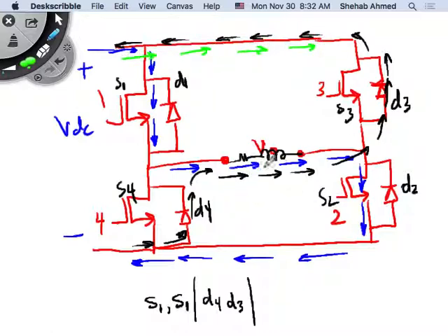Remember this now, the inductor current here is now being opposed by the DC supply. Initially it was supplied by the DC supply. Now there's voltage opposing current. So what was happening to the blue current? It was decreasing in value. You have an inductor and a voltage source opposing it, so the current is decreasing in value. And now the green, after you've exhausted that energy in the inductor, you flipped the polarity of current by turning on S3 and S4.